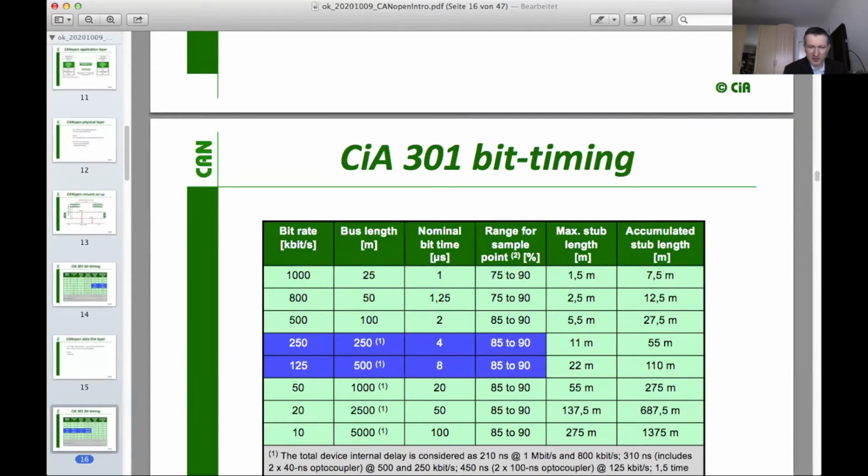For each of these bit rates available for Lift and also for the other CANopen devices, you have the very exact constraints where you have to choose and how to configure your CAN controller for use in CANopen and in CANopen Lift components design especially.